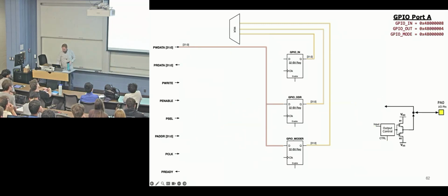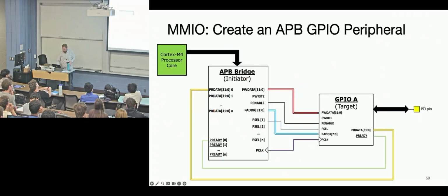And so the other big thing that you need to get your head around is how the core goes. We didn't really talk about how the core actuates the bridge. Let's just say that happens, right? The core does a store, then these lines go high, low, whatever they're going to do. Messages get sent across these pins, this bus, and then into registers here, those registers I just showed you that you guys drew to control that pin. So understanding that whole data flow is critical for this class.